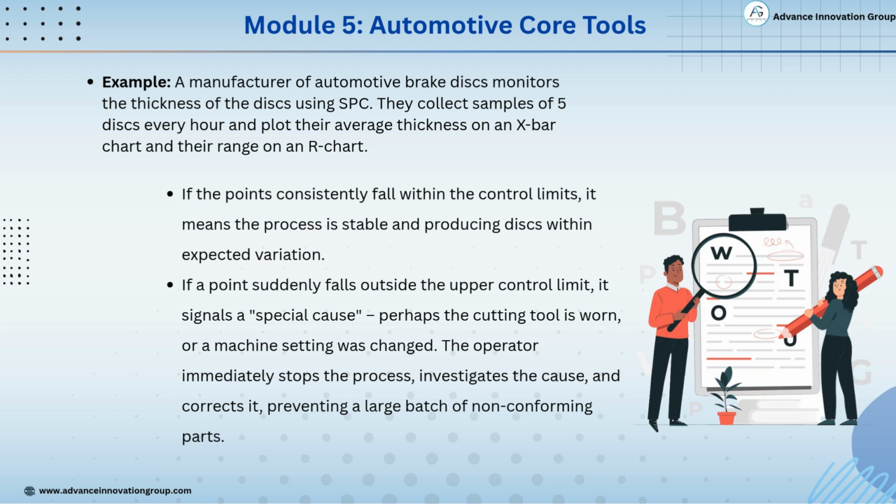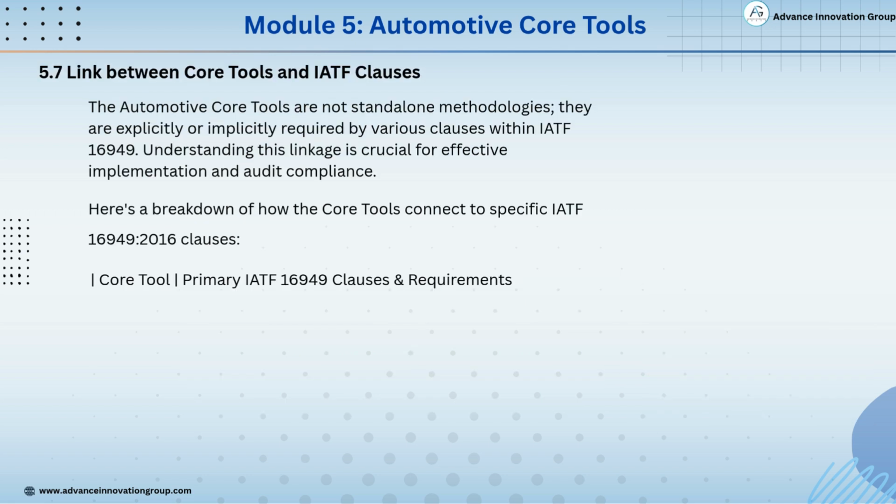For example, the cutting tool might be worn out, or a machine setting may have changed. In such a case, the operator immediately halts the process, investigates the root cause, and fixes the issue to avoid producing faulty discs.